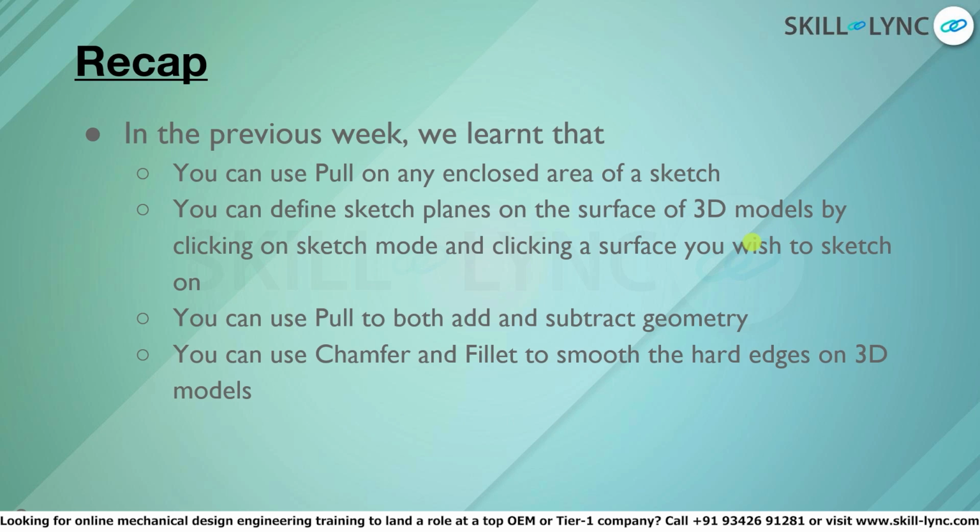In the previous week, in week 2, what we learned was that you can use the pull tool on any enclosed area of a sketch. So if your sketch has multiple surface areas, you can use the pull tool on any one of those enclosed areas or on multiple of those enclosed areas using a multiple area selection using the Control and Shift keys with clicking. We also learned that you can define sketch planes on the surface of your 3D model by clicking on sketch mode and clicking on a surface that you wish to sketch on.